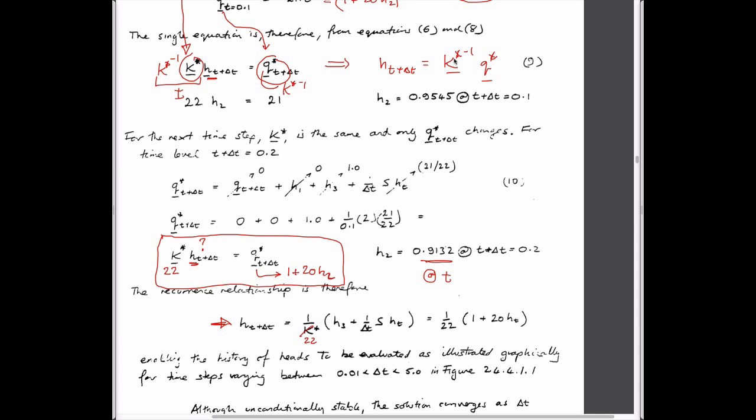There are much more efficient ways to do it than inverting the matrix. We're solving a matrix. But in doing that, we're actually using much more effort than if we never do that step. So the reason for using explicit representation is that we can solve the system incrementally. We may use more time steps, but in each of those time steps, we actually don't have to keep on solving this equation. Of course, if it's a linear system and the permeabilities, hydraulic conductivities don't change, then we actually have to solve this only once and then do the back substitution. But it still takes more effort than doing it explicitly.